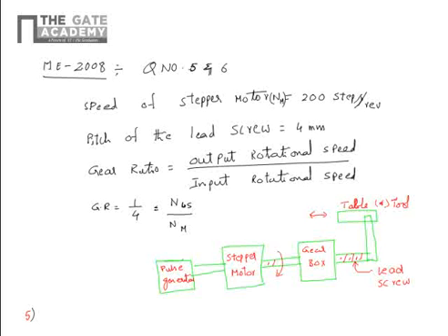Calculate the BLU, basic length unit, which is the table movement corresponding to one pulse of the generator. One pulse of the generator is equal to one step of the stepper motor.